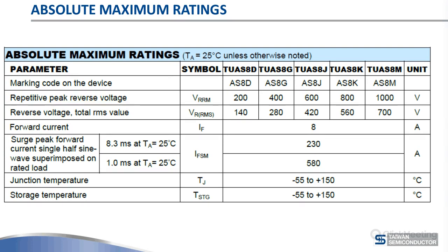Well, those conventions are about 30 or 40 or 50 years old, when a lot of linear power supplies were still around. These days, everybody uses switch mode power supplies, and your input surge rating is more in the area of 300 microseconds or 500 microseconds. So this 1 millisecond value is a little bit more helpful for you to judge what maximum surge your device will be able to handle.